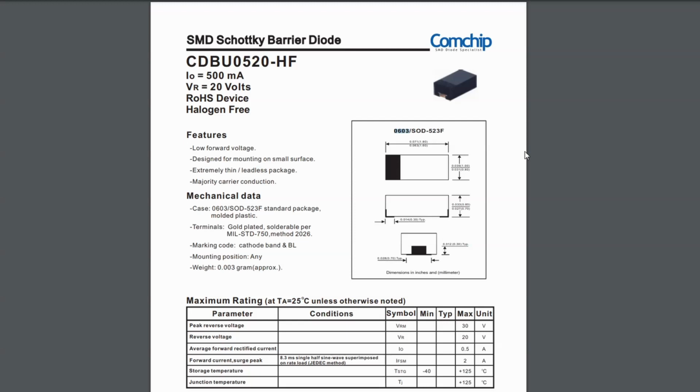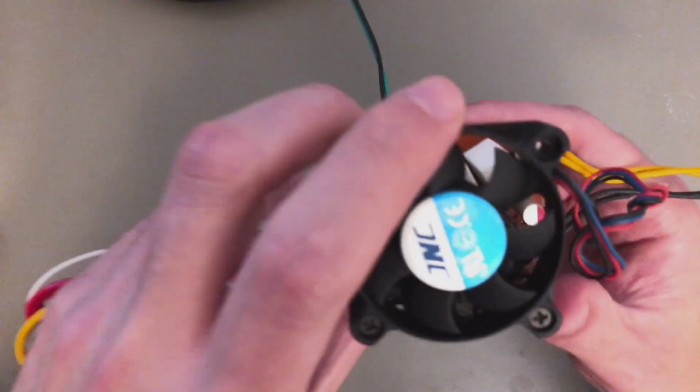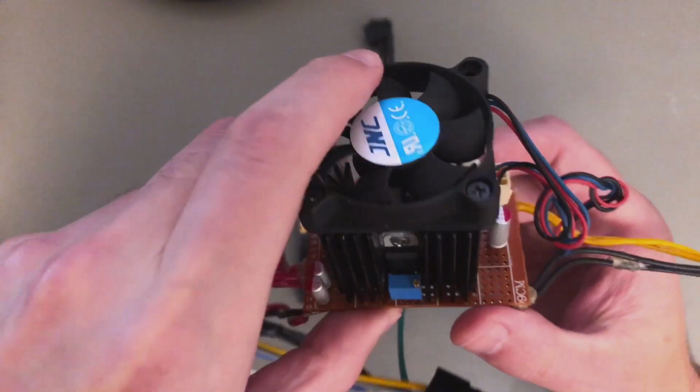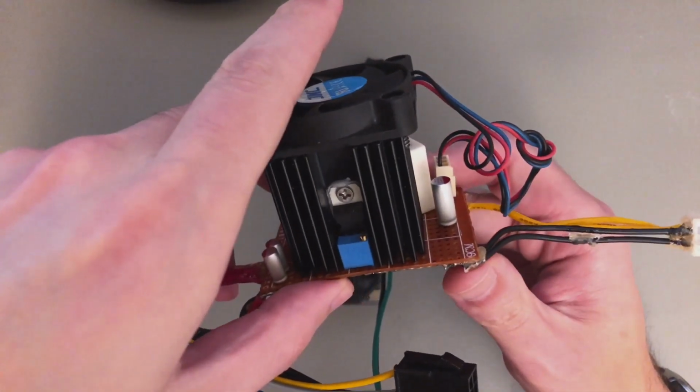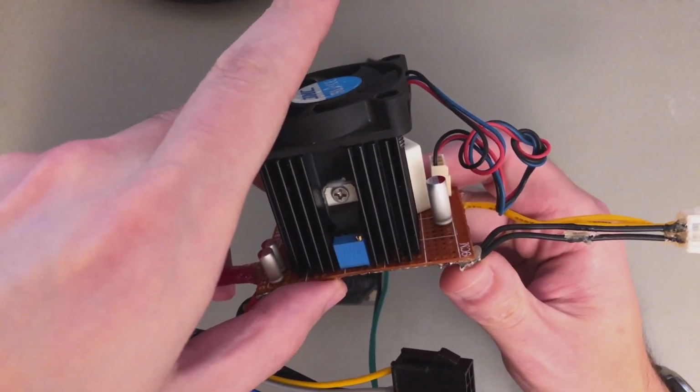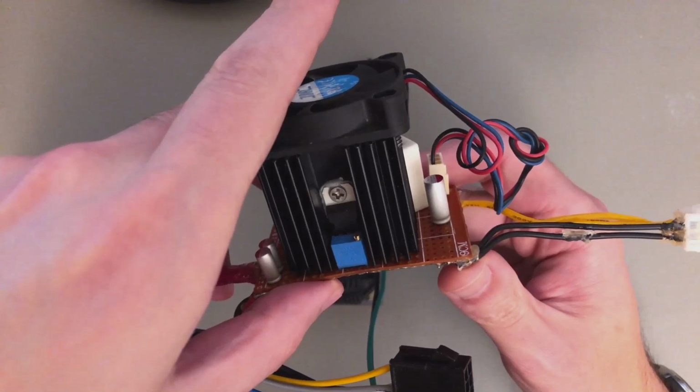So then of course I can raise the voltage even higher by placing more diodes. This in the general case will not work because of the 1.4 volt minimum dropout of this voltage regulator. In my case for sure I can eliminate this problem with my little device here that can just provide the motherboard with something like 5.4 volts.